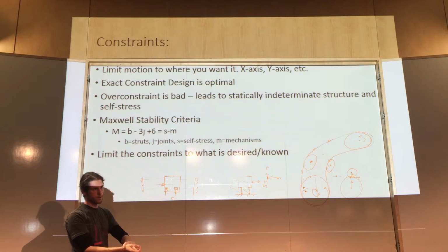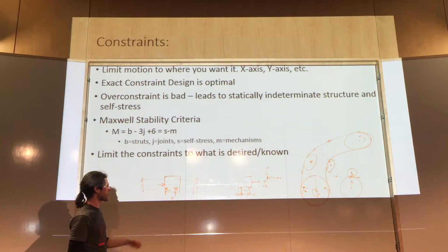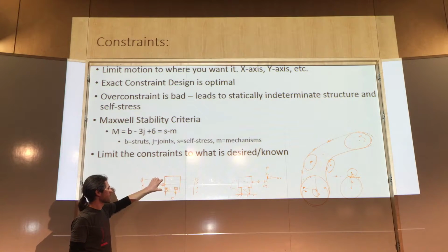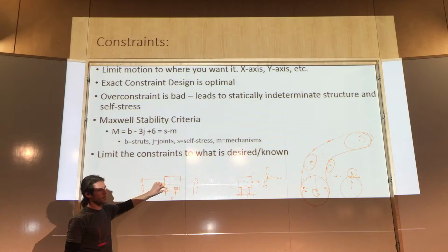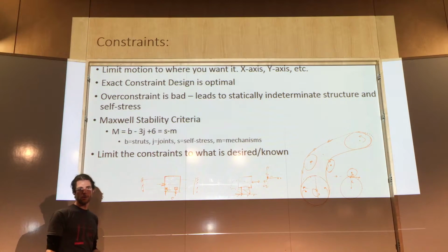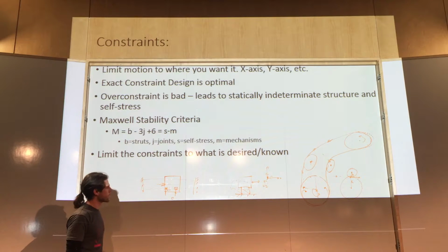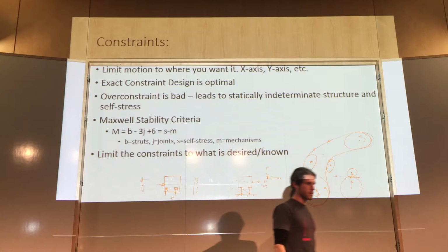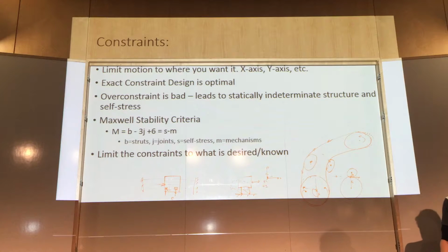I have some stiffness of that beam. I need to be sure that those joints are going to withstand the load, so I'll size my bearings and the constraint system around that in order to balance out those forces. And of course, I want some headroom on top of that. So that's just a really quick way of looking at this idea of constraints. You kind of want to sit down and draw out a free body diagram of what you're working on, so you have a sense of how accurate it needs to be.